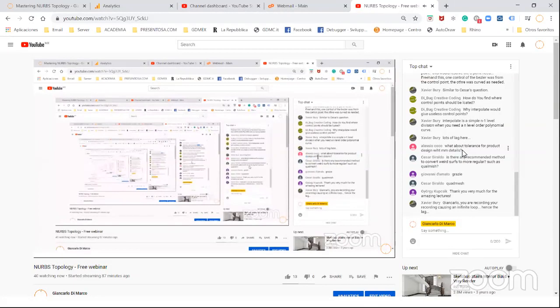Every time you perform a rebuild, for example, you are deforming the curve also at a very fine detail level, and you are basically screwing the tolerance up. So you might want to double check that the resulting geometry still works inside the tolerance that you have in your document. That's the main aspect about controlling tolerance for product design.